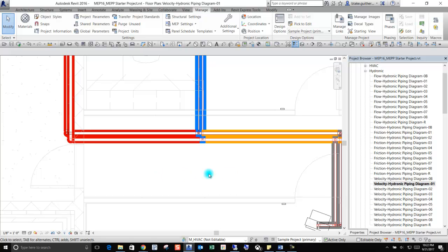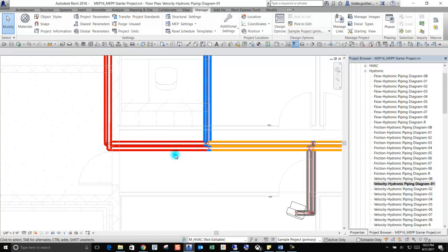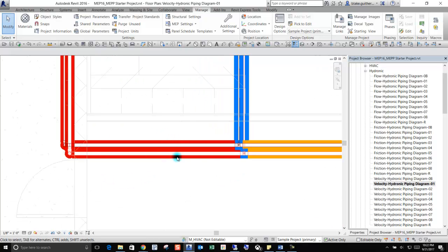So with Revit, you also have to be aware that it is showing peak connected flow. So if you're sizing your pumping system off of a block load where your pumps do not equal the peak, well, then your designers need to be aware of that.